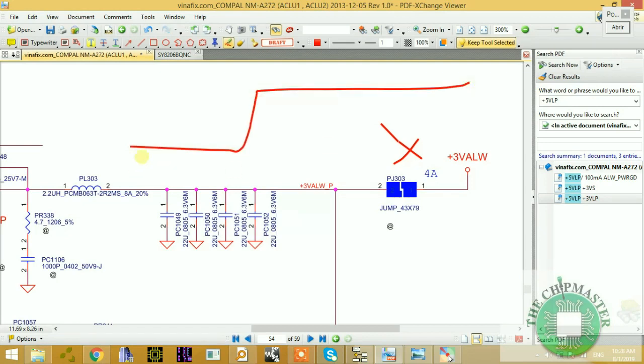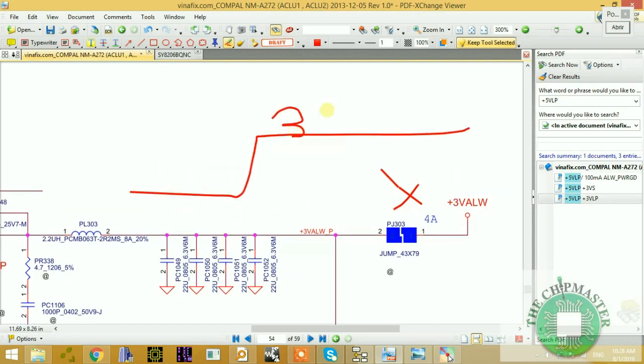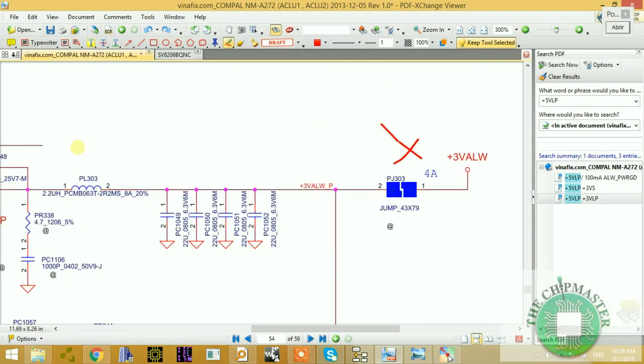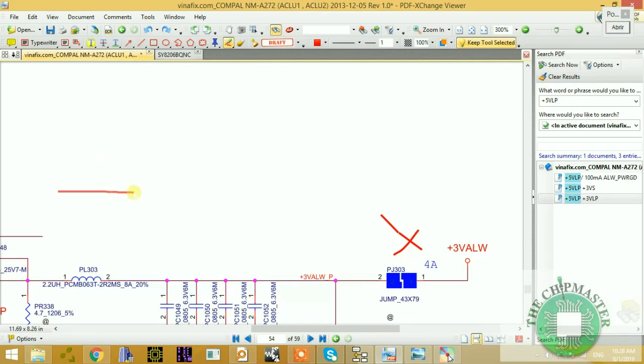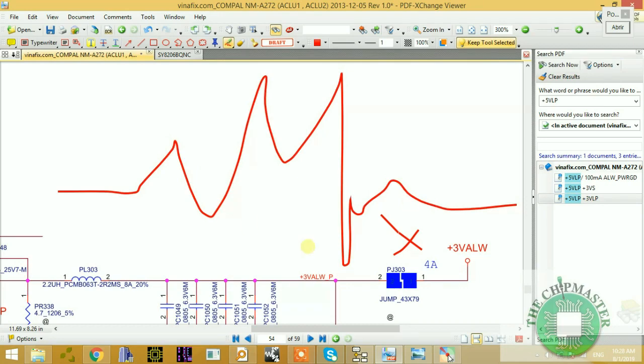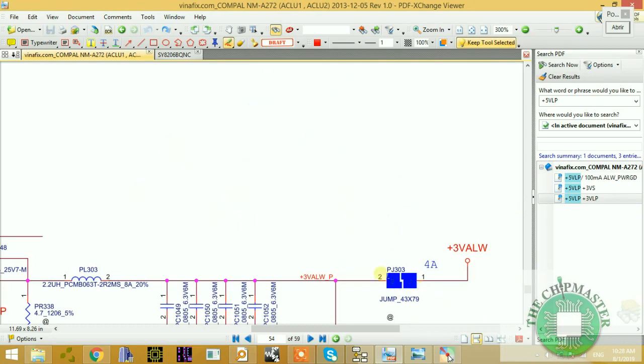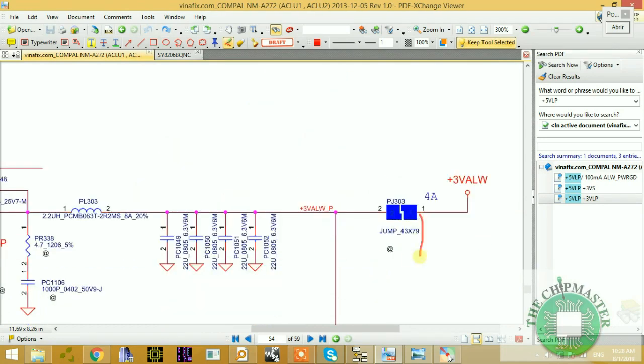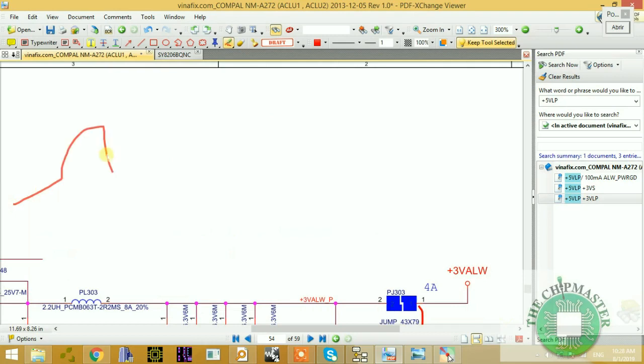So that is a normal 3 volt. All right, that's a normal 3.3 volt working condition that is satisfied. If there's an over voltage, you'll get something like this on the oscilloscope. That indicates that there's a fault. Most times on other motherboards, there will be a filter capacitor on the outside that is connected to ground. That filter capacitor will be leaking, and it will cause the over voltage protection on the oscilloscope waveform.